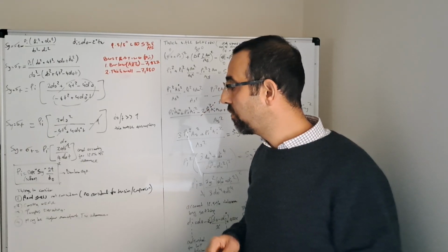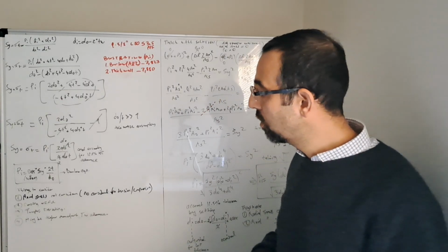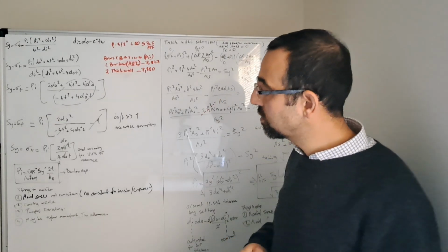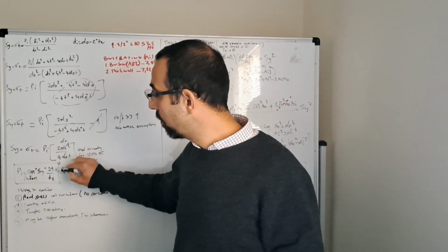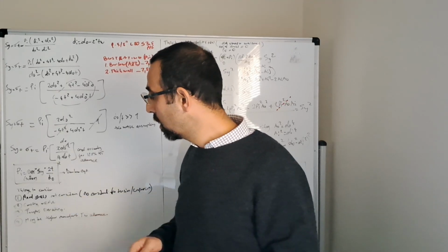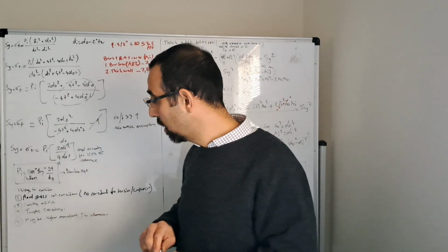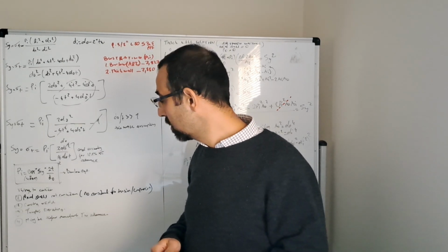However, that could also affect the wall thickness of the casing. So when you do a corrosion log or something, then probably this value will be a better known measured value rather than a value that you predict on a casing wear, which is quite difficult.